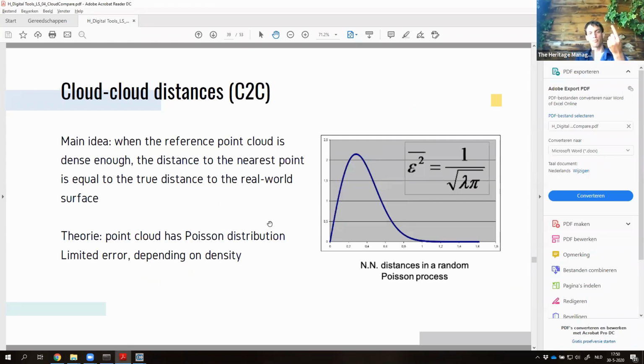will have is that if you take 1 point from 1 point cloud and you compare it to the closest point in the other point cloud, that this distance is by default always positive, because the distance in 3D is always positive. You cannot go in the opposite direction. But that will also depend, the quality or the results will also heavily depend on the resolution of your data.